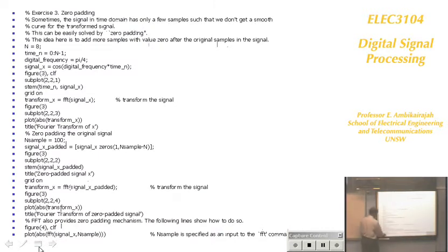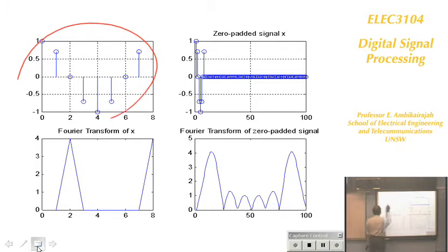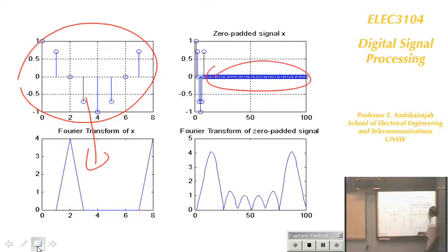So this graph is shown on the next page, and the MATLAB program is written as well. You can find this out in MATLAB: this is the original signal, that's my spectrum. It looks like that. Then I added lots of zeros at the end and got the Fourier transform. It did a lot of interpolation, and the waveform looks nicer. It's the same signal, same information at the peak; the value should be the same.